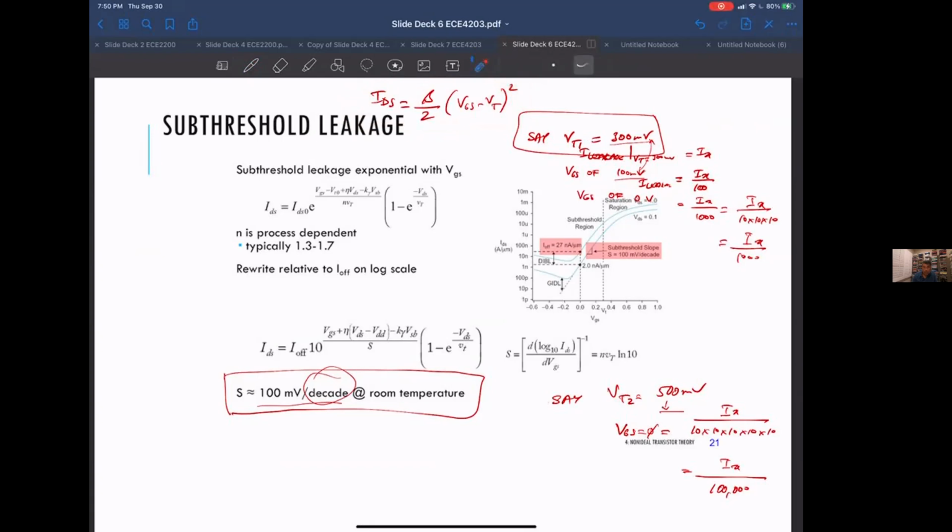The on current decides how fast you're transitioning between 0 and 1, which means how fast you can operate your circuits. So the lower the threshold voltage, the faster you can operate your circuits, because you'll have more current to charge and discharge these capacitive nodes. But you're going to have to do that at the expense of leakage current. Again, all things being equal, more things go into this, but that is what you'll see a lot.